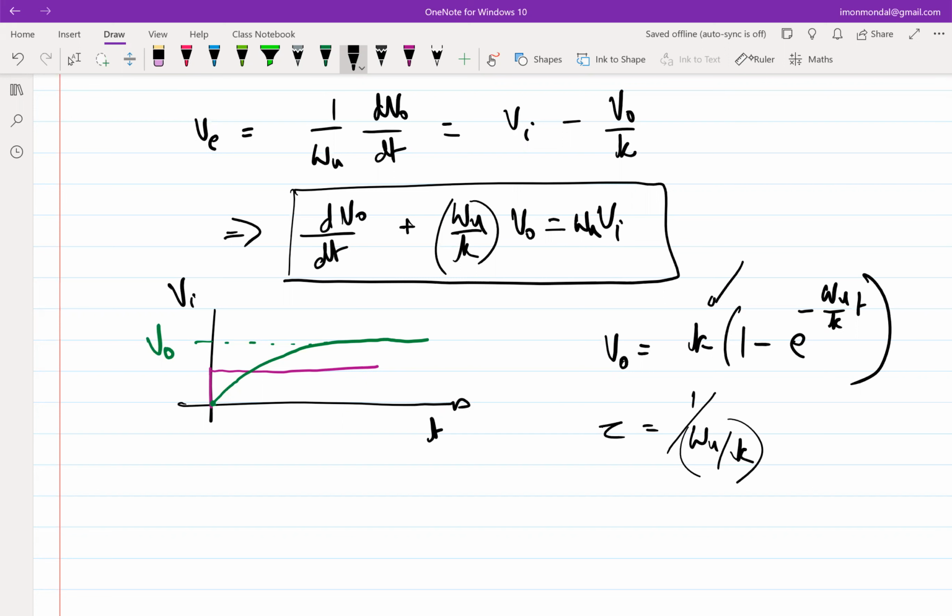So this is as far as the dynamics of a first order negative feedback loop is concerned. I say first order because you only had one integrator in the loop, right? So obviously you had a first order differential equation, and this is the settling of a first order negative feedback loop. Okay. And by the way, can you comment on the rate at which this output changes at time t equal to 0? What is the slope?